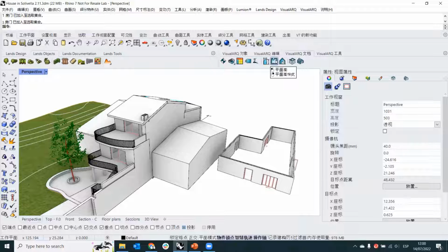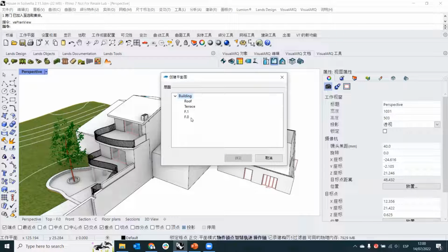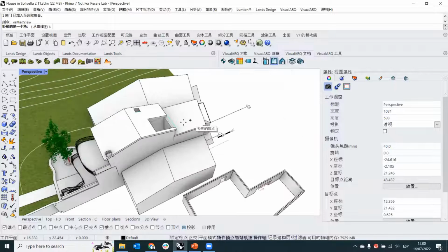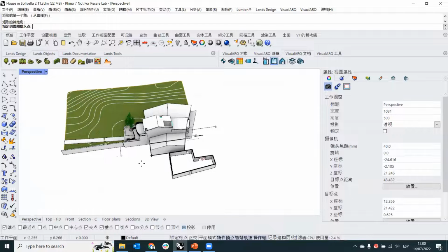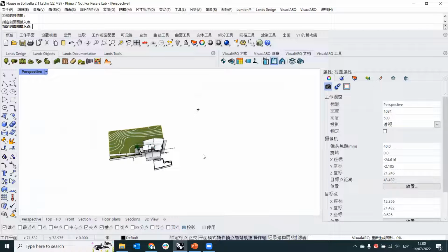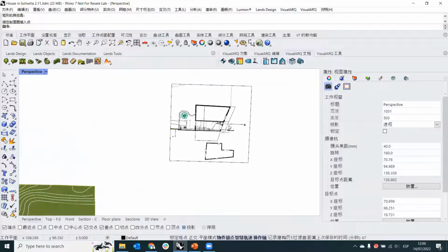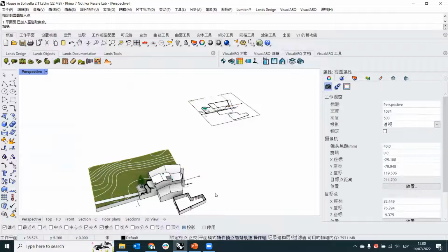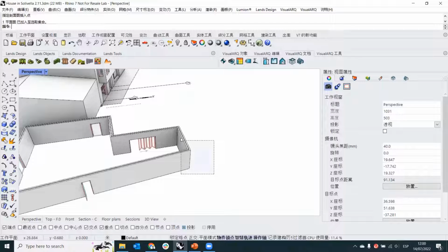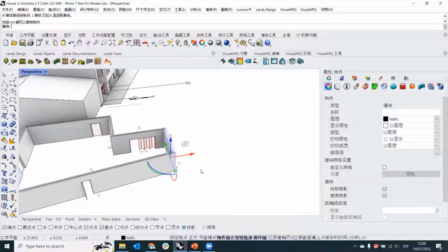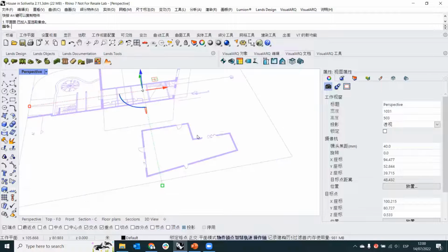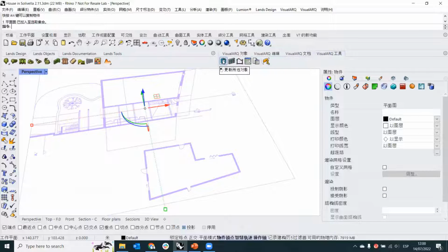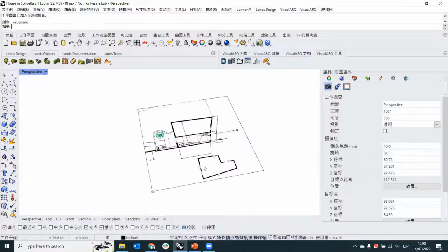We can also generate a plan view. We select the level we want to display. We select maybe all this drawing and insert that into one point in the modular space. So this will be just a 2D block linked with a 3D model. Any change that we do here, for example, we stretch this room by moving the control points, and later on we can just come here and update this plan view, and everything will recalculate all the changes done on the 3D model.